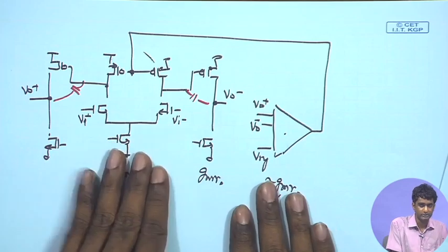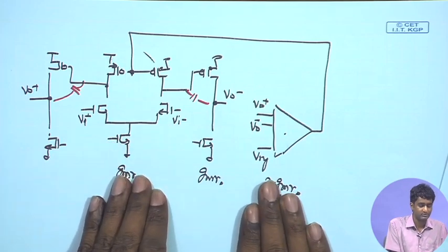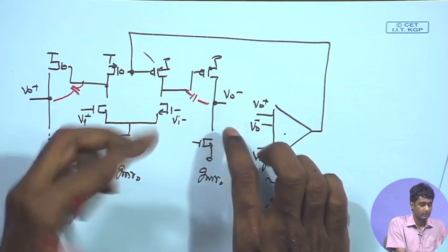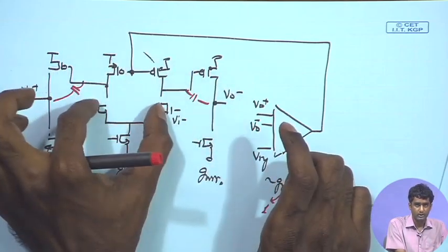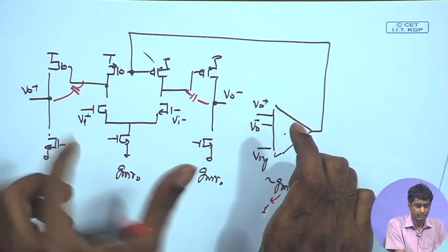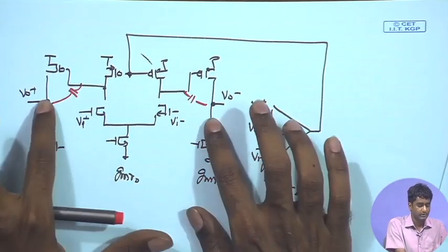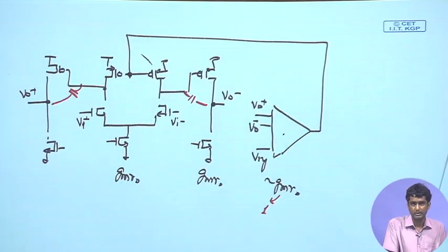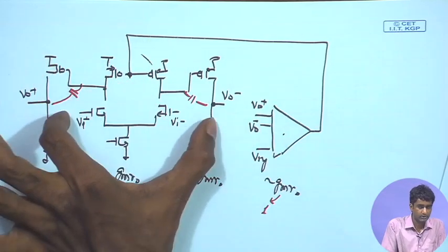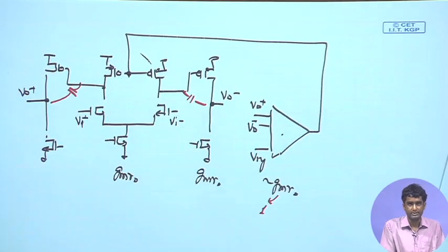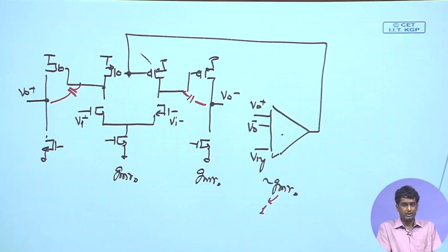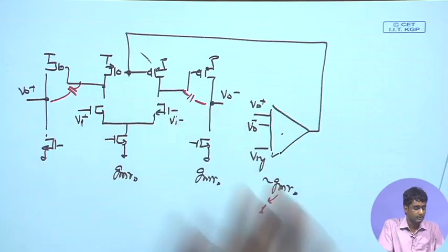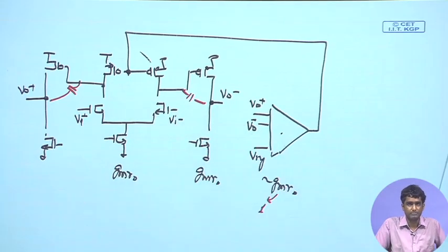We will look into these examples also in simulation exercises. We will analyze both cases: where we have common mode feedback for the two stages separately using two error amplifiers, and the other option where we have a single common mode amplifier doing the compensation for the entire common mode setup for the final stage as well as the first stage. There are a couple of trade offs related to this choice. Probably that will be more clear when we look at the simulation examples.